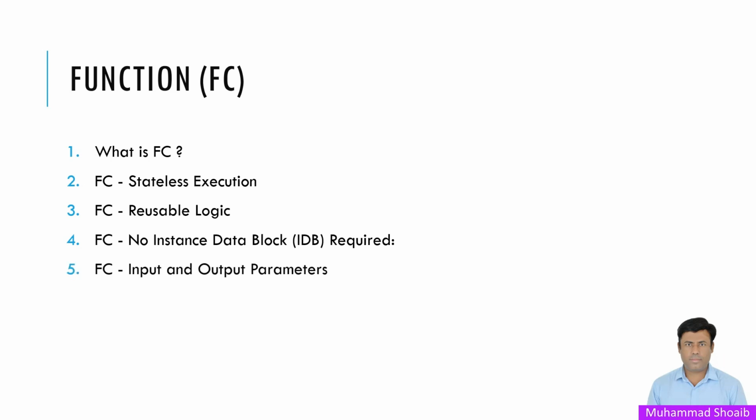Then the input and output parameters. FCs can have input, output, and input-output parameters, allowing flexible data exchange between the FC and the calling program.